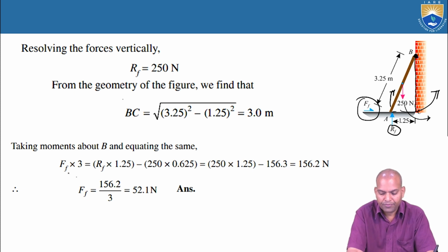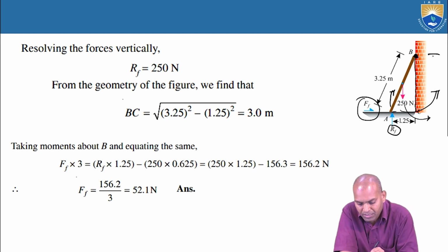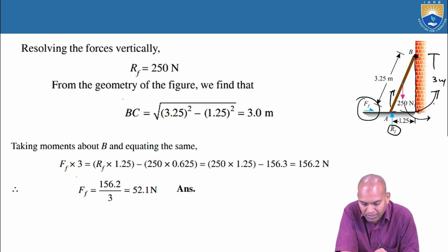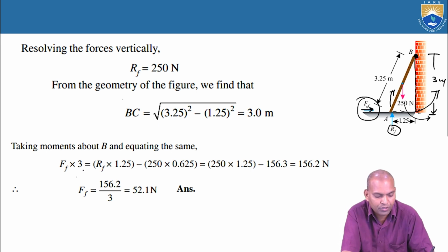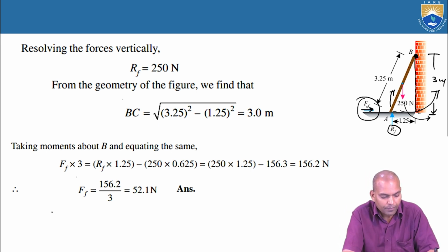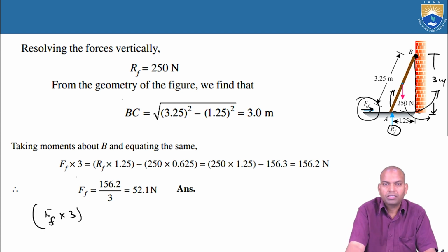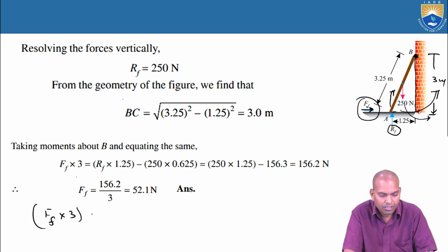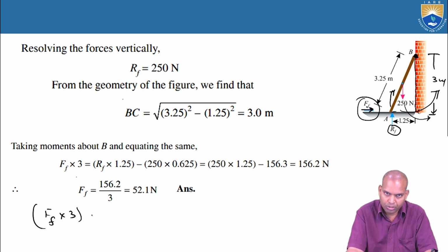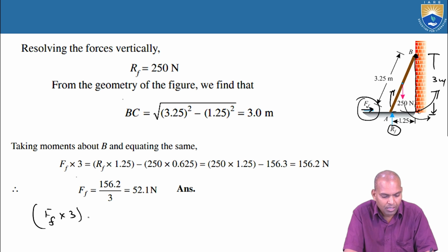Now FF into what is the distance here? This FF into 3. This is 3 meters perpendicular. FF is the force into perpendicular distance. Yes, FF into 3. It is in which direction? Counterclockwise direction. Counterclockwise moments equal to clockwise moments.